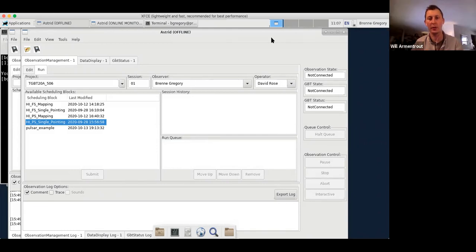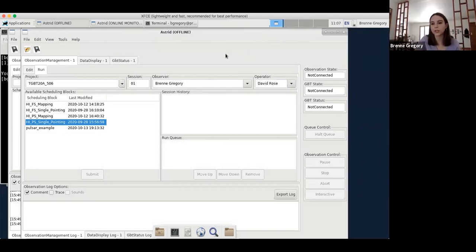Sometimes at high frequencies, we will build up focus or pointing corrections from lower frequencies. Like we might point at 10 gigahertz first, and then go to Argus to point at 90 gigahertz or so. So we get that initial correction and then can correct further at higher frequencies. And most of the time when you're looking at your pointing, it'll be pretty obvious if something's going wrong. But again, that comes with experience. All right, I'll go ahead and stop my share and then allow Amber to take control.